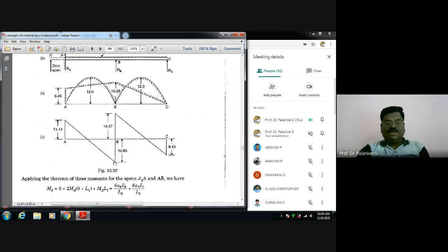Okay. Again, the support reaction at B is upward. This much value totally it goes. Again, there is a UDL acting which is downward. Again, triangular. Okay, linear variation should be there. So this much. The support reaction here is 14.57 minus this one. Only this ordinate you have to take: 14.57 minus 6 into 4 here will give you minus 9.43. So minus 9.43 comes here. Again, the support reaction RC is 9.43. That's why the shear force diagram goes up to this one, center.